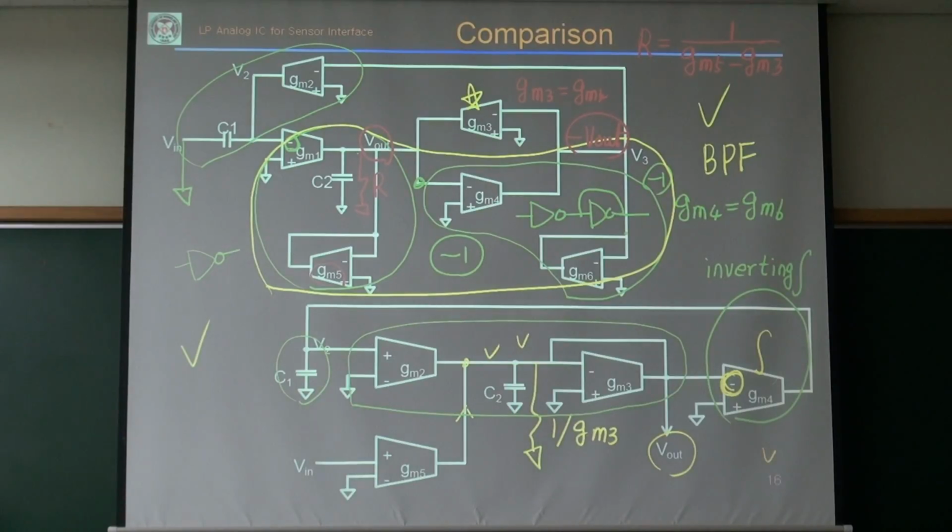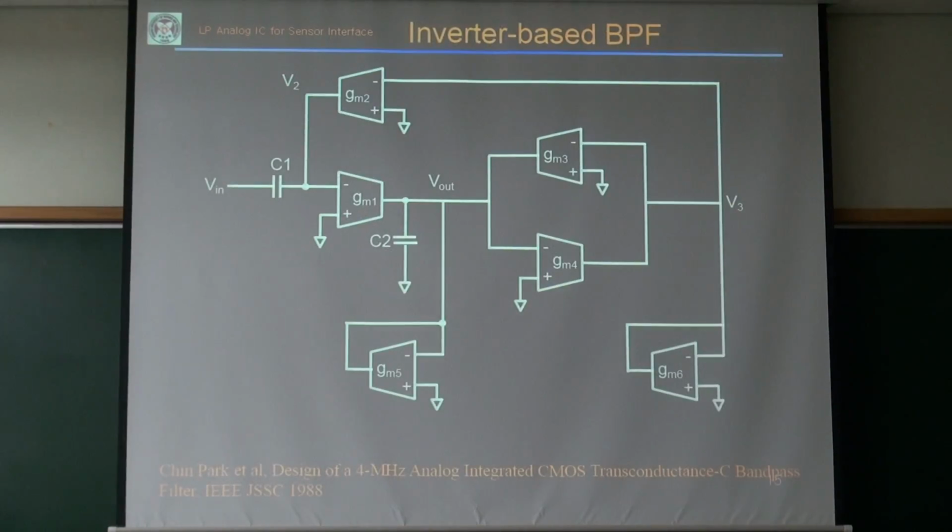Let's see, I will go forward. For this thing, look at this, this is Vout, and this is 0. Actually, this is just an inverter. Because of this minus input, this gm5 Vout will flow in. And because this is minus Vout, because of gm4 and gm6, this polarity inverter, current must flow in, okay? It is true.